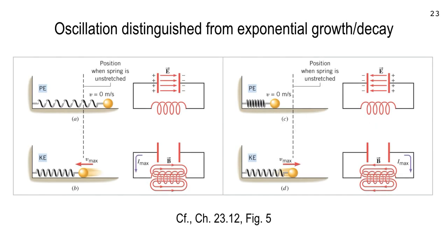And here's the exact analogy. This is not a diagram in our book, but go ahead and make a note. The potential energy in the spring is like the capacitor, and this one uses a spring-like symbol for the inductor and parallel plates for the capacitor. You can see that it goes from a lot of energy stored into a lot of energy in use. The kinetic energy term is the inductance term.